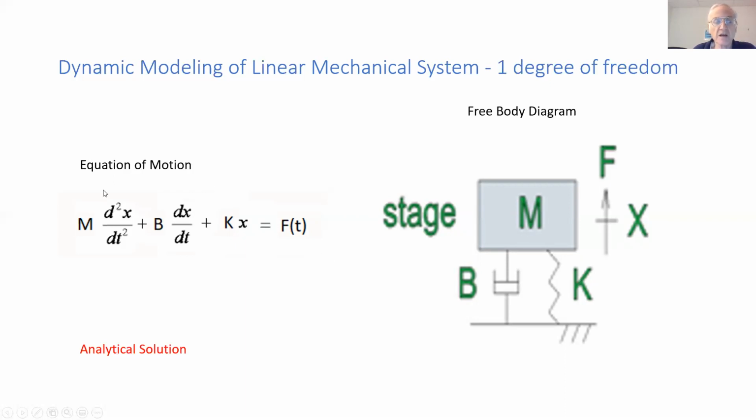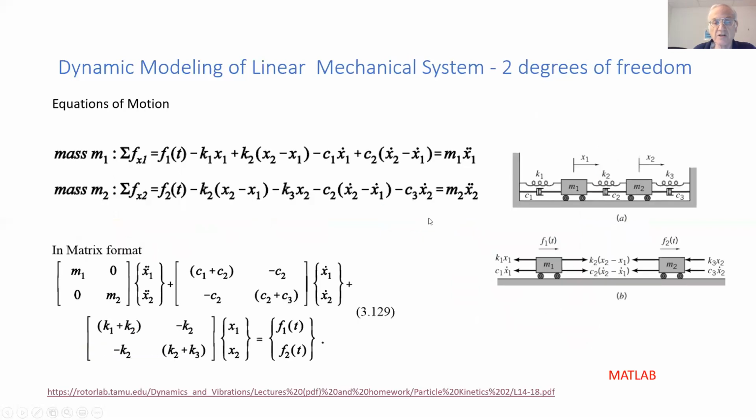And that is the equation of motion: mass times acceleration equals the spring force and the damping force. We bring them to the other side, and we equate that to the forcing function. So that is the summation of forces equal to 0, and the forcing function is equal to all the resisting forces, which are inertia, damping, and stiffness.